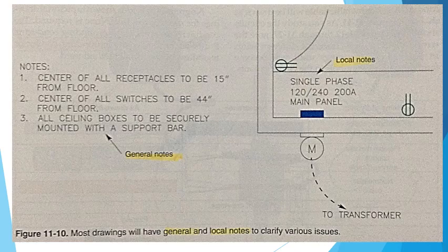Although the prints have lists of materials to be purchased, the specifications will also have a similar list. If the lists do not match, the specifications are typically followed. This is because a print may be used for multiple projects, but the specifications are the documents that are created for a specific project.